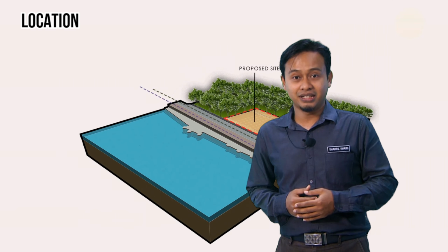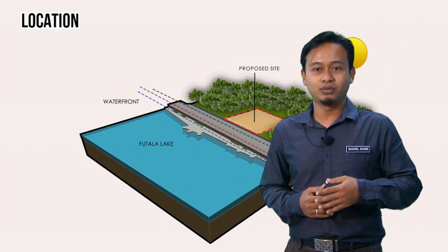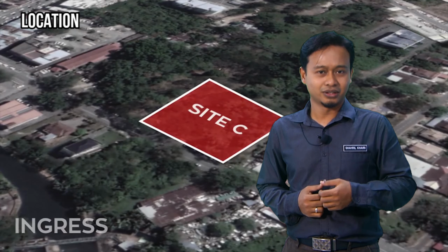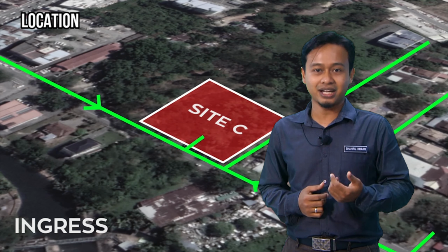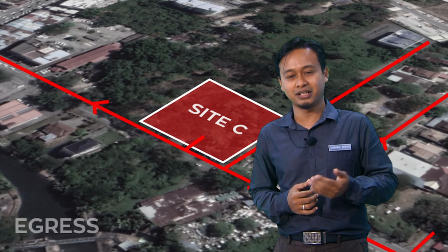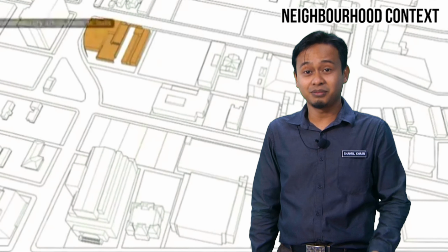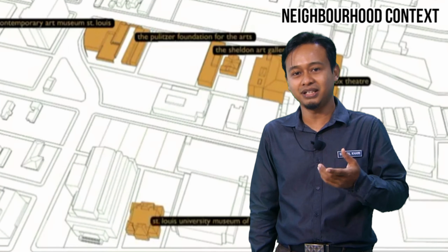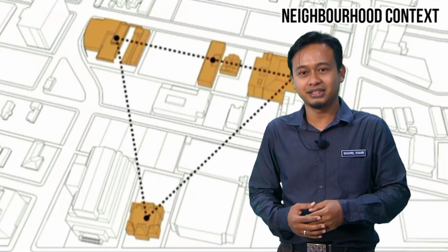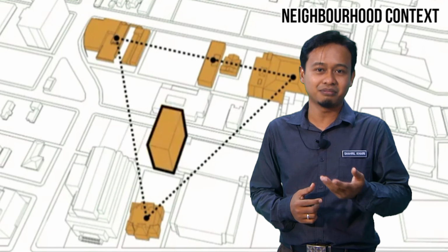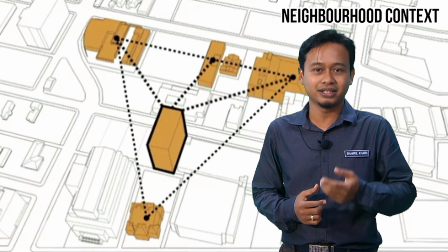Location is the place or position that something is. We need to take into account geographical site location details, the lot numbers, road names, address, major landmarks, and current context such as existing buildings, car parks and roads. For neighborhood context, we must consider previous use of the site and how that could impact the current condition. Observe and research the significant buildings, structures, materials, spaces and landmarks in the local area, and include an annotated visual or photographic representation.